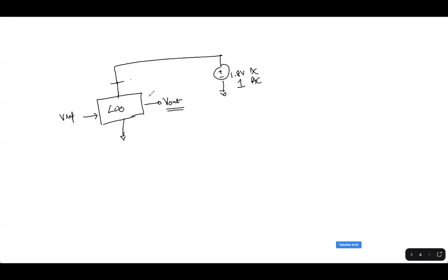When we give AC 1 and run AC analysis, we don't do STB analysis, we do AC analysis. Initially it runs a DC simulation. It may not really show you that it has run a DC simulation, but it makes sure that it runs one to set the operating points. Once the operating points are set, it will run a frequency simulation, or AC simulation, across the specified frequencies, where only the AC will be applied at the supply.